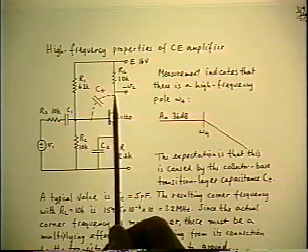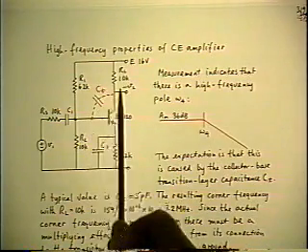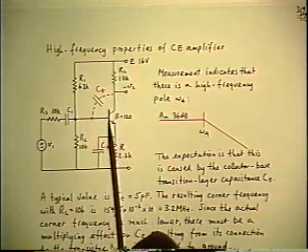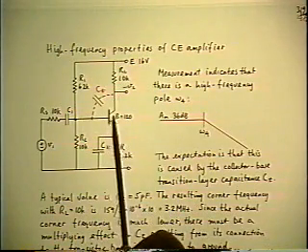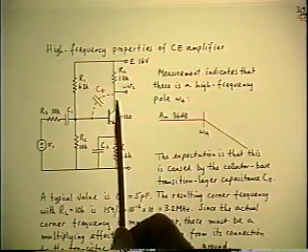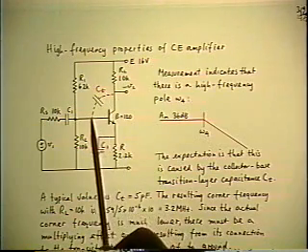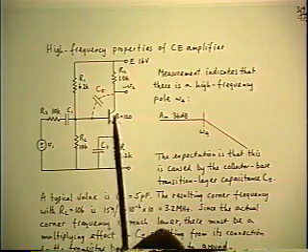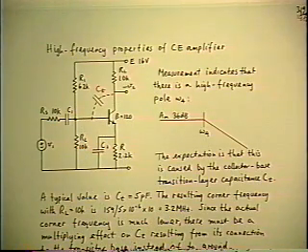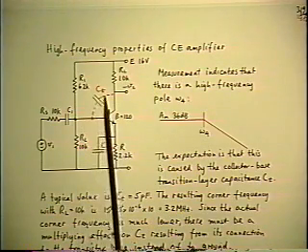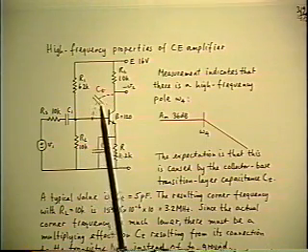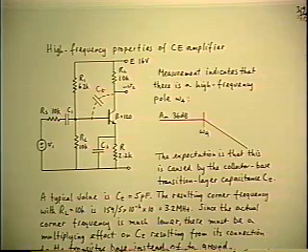Only one end is connected to the RL. The other end does not go to AC ground, as RL does. The other end goes back to the input of the transistor, which means the current that gets diverted from the output through the CT doesn't go to ground. It goes back into the input and it gets re-amplified. So possibly the effect of the CT is magnified over and above what it would be if it were directly in parallel with the RL.